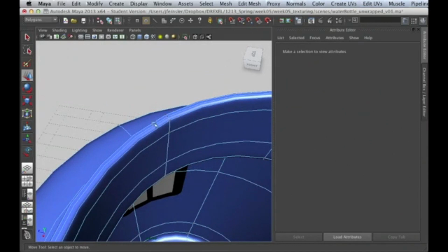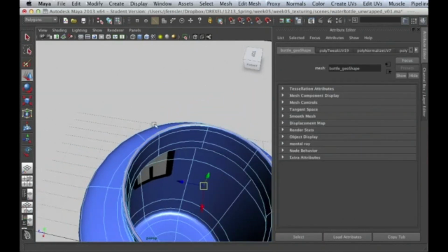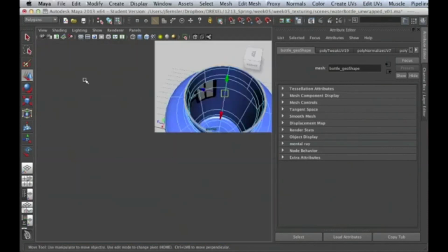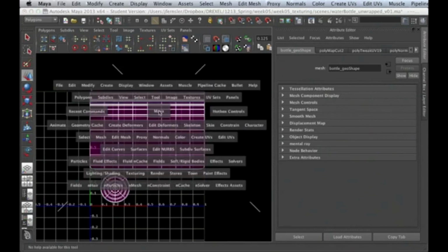and we will head back over to our viewport, and we'll do what comes logically next, which is to take this edge here, where it's the beginning of the inside and the end of the outside, and I'm going to double click that edge, right? And we get the edge loop. That selects the whole thing, and pop over to our texture editor. You can see right here at the top, there it is. And I'm going to use our cut UVs along selected edge. Right, now that generates two shells.